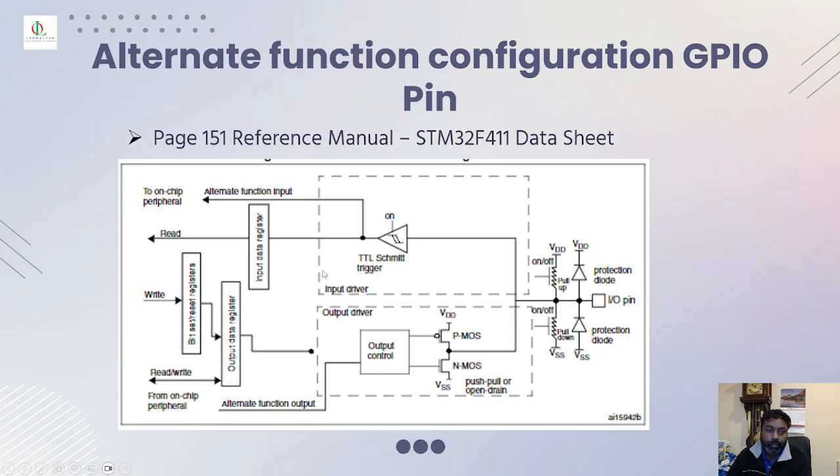And this is about the alternate function that you just saw. Alternate function low, alternate function high. Alternate function low covers bits 0 to 7, and alternate function high covers bits 8 to 15. Out of the 16 GPIO pins that we talked about, the first 8 bits, when you want to use them as an alternate function, are considered low, and the last 8 bits are considered alternate function high, sorry.